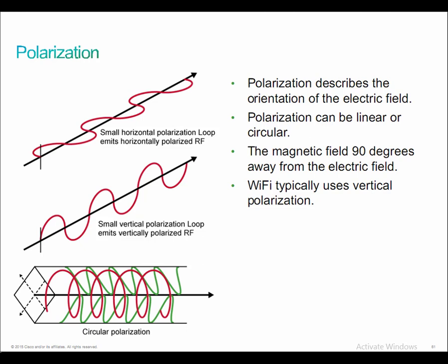The polarization of the electromagnetic wave is going to refer to the direction of that electric field. That's what I was just describing in the book there. Like I said, in linear polarization, the field oscillates in a single direction. In circular or elliptical polarization, the field's going to rotate at a constant rate in a plane as the wave travels. The rotation has two possible directions, right-hand sense or the left-hand sense. And again, not something we typically have to concern ourselves with in wireless, because we typically use just vertical polarization.